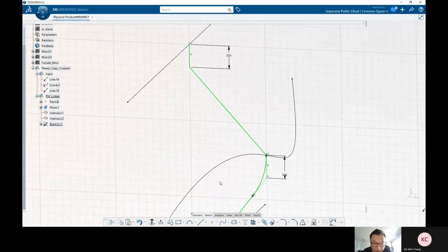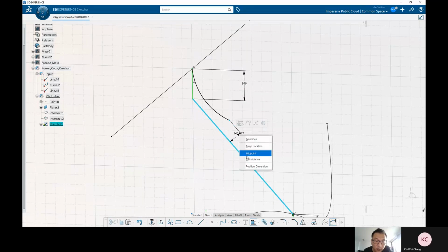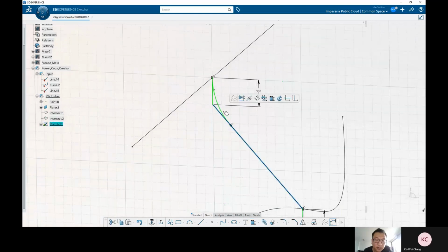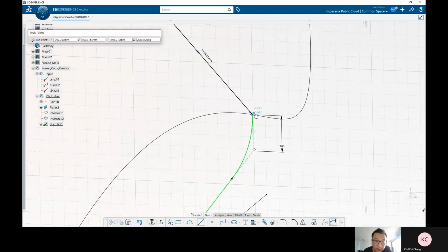And we create the arc starting from here, like this. So avoid over constructions so that you can define yourself what you want. Coincidence, cross, tangency. And then here, tangential again. So change it to constructions, and add the line from here to here. Okay, I think it's good.